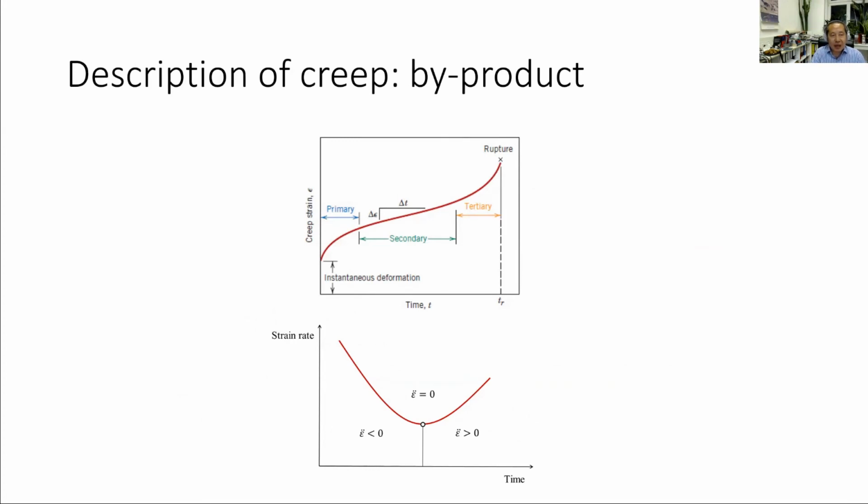Now I want to have a look at creep. We know that creep is very important for softer soil, for rock, for everything, and for softer soil in particular for the stability check of slopes. Have a look at softer soil: you get a creep strain over time. We got 3 stages: a primary creep stage, a secondary, and sometimes a tertiary creep towards rupture. That's what we have.